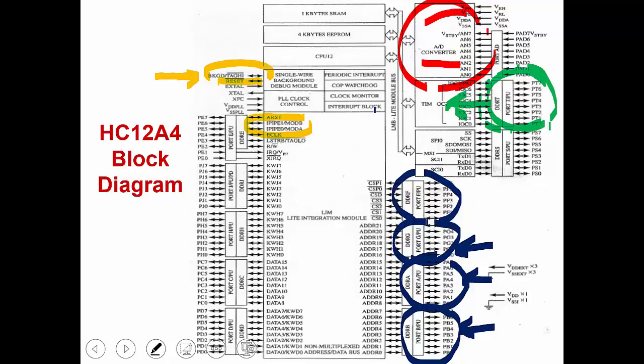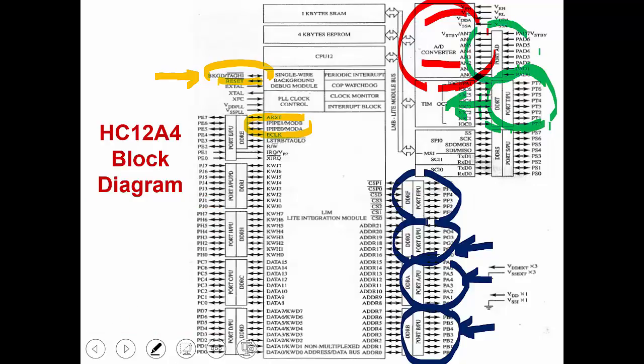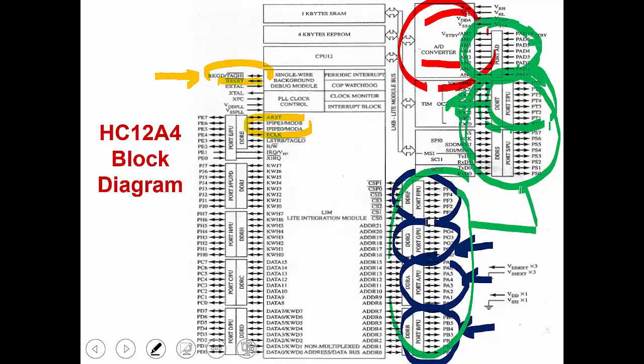We can configure them to be input like those. Let me show you. Like those ADC conversion ports, they're only incoming. See, they're only input. For those, they are external input or output. For those and those, here we go. If they're designed to be bidirectional, then we can change individual bits, for a specific application, to work as input pin or output pin. So in other words, we can change the port channels to be input channel or output channel by changing the corresponding register.